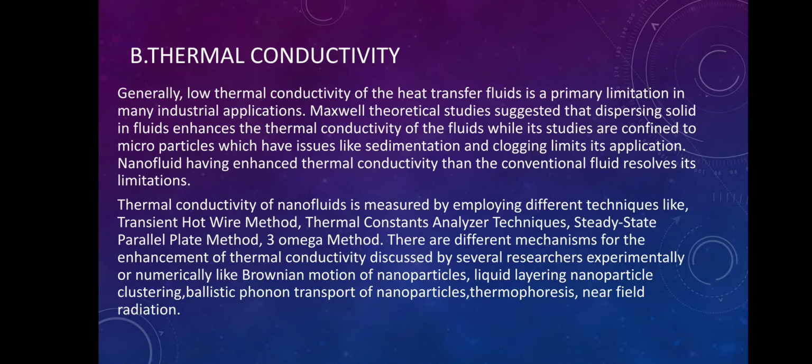Thermal conductivity. Generally, low thermal conductivity of heat transfer fluids is a primary limitation in many industrial applications. Maxwell's theoretical studies suggested that dispersing solids in fluids enhances the thermal conductivity of the fluid, while his studies were confined to microparticles, which have issues like sedimentation and clogging that limit their application. Nanofluid, having enhanced thermal conductivity compared to the conventional fluid, resolves this limitation.